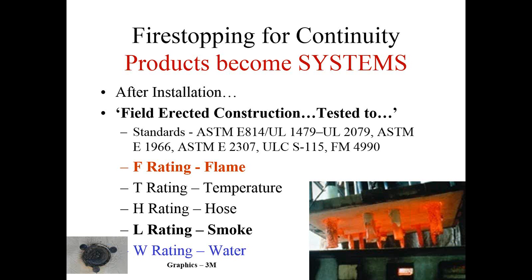Fourthly, there's been no water spray or hard water put on that assembly immediately after it's been installed or a day after it's been installed to simulate what happens in buildings. They don't put the windows in on new construction until after, many times, the firestop's been installed. How does the system resist that? So these are some of the things to be aware of when specifying this W rating, and also the L rating too.